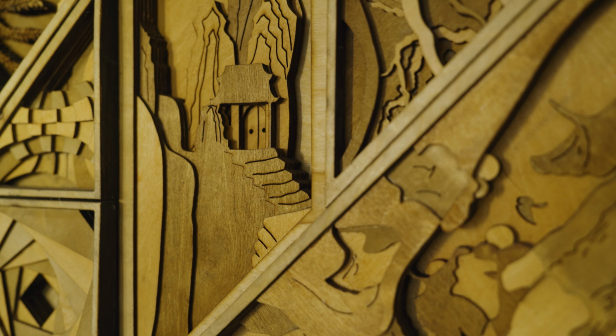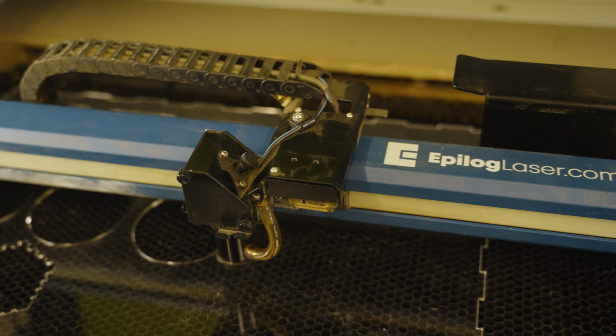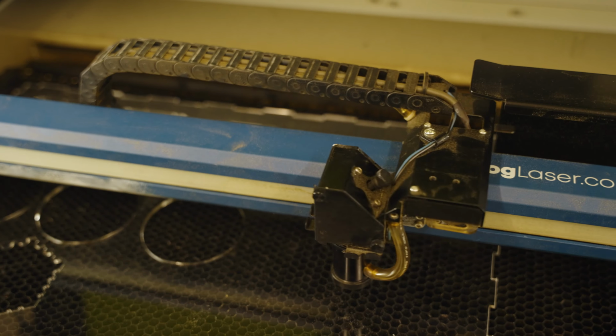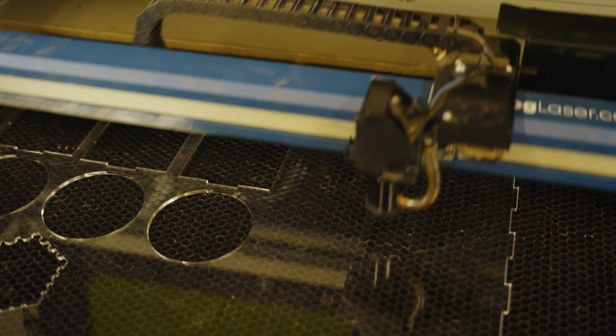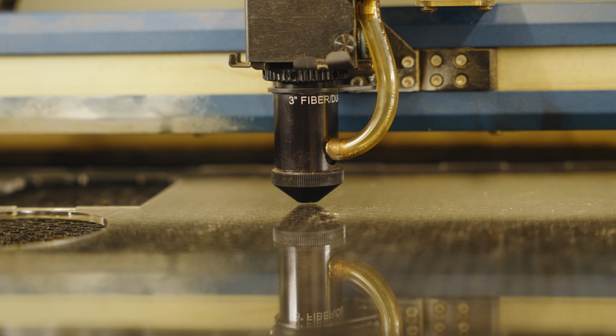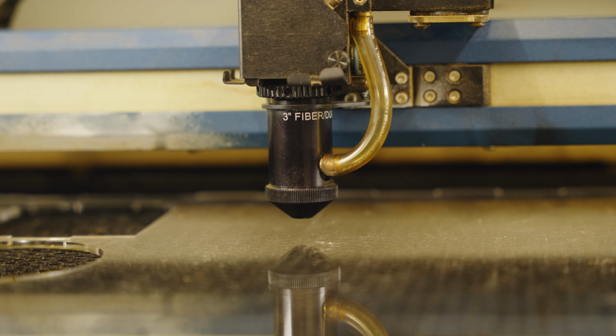Our CO2 laser cutters are one of the most common types, where the head is on an XY CNC gantry that moves around to cut or engrave your part. The bed of the laser cutter moves up and down to put the top surface of the material at the focus point of the laser. This is a simple and robust system that allows the laser cutter to cut and engrave material quickly and efficiently.